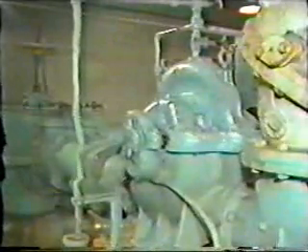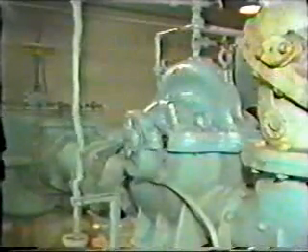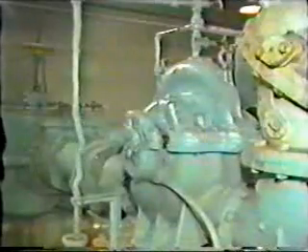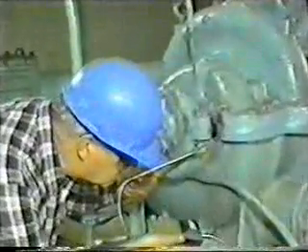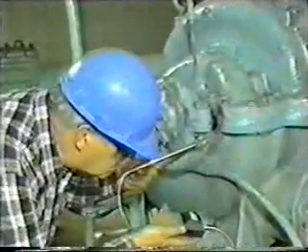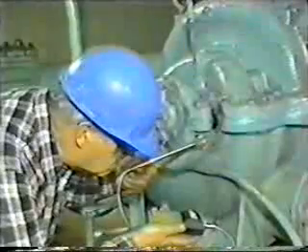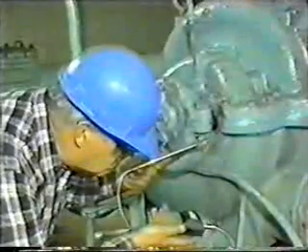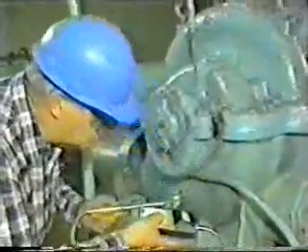For this particular problem, check the area around the bearings for evidence of lubricant having been forced past the seals. Overgreasing could result in overheating. The area on this pump looks properly clean. Check the temperature on the bearing. Follow your facility procedures for making this type of check. In our case, Gene uses a pyrometer to get an accurate temperature reading.